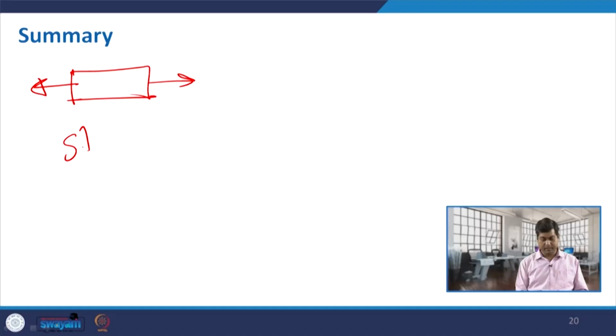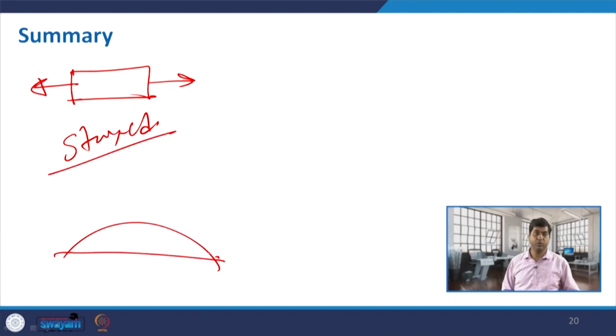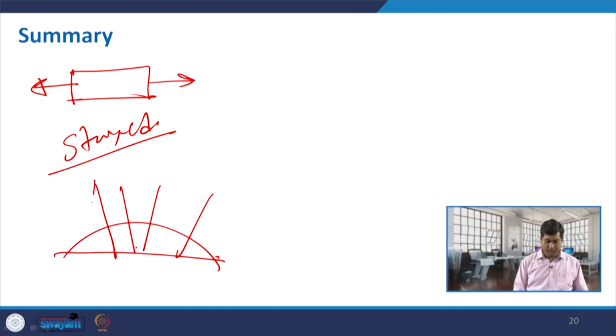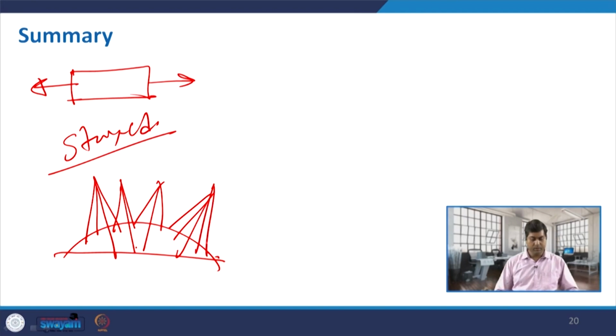Depending on the position and the members used and the way they resist the applied forces, we have some categories. We started with the straight cable, like the example I gave with the Millennium Dome, where the large span is divided, there are supports as compressive members, and the whole roof is supported with the straight cable.